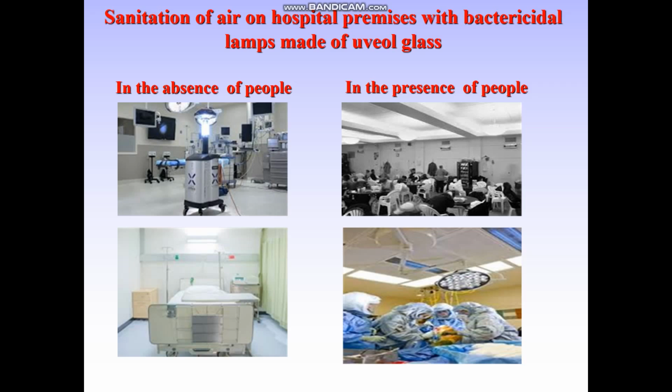Therefore, only the upper portion of the premises is irradiated. Shielded lamps are usually placed evenly all about the room at a height of no less than 2 meters above the floor, in places with the most intensive convection of air, for example above heating devices, doorways, and window frames. The total duration of the irradiation of air indoors should not exceed 8 hours per day. The optimal mode of irradiation should include hours of irradiation alternating with breaks to air the room.